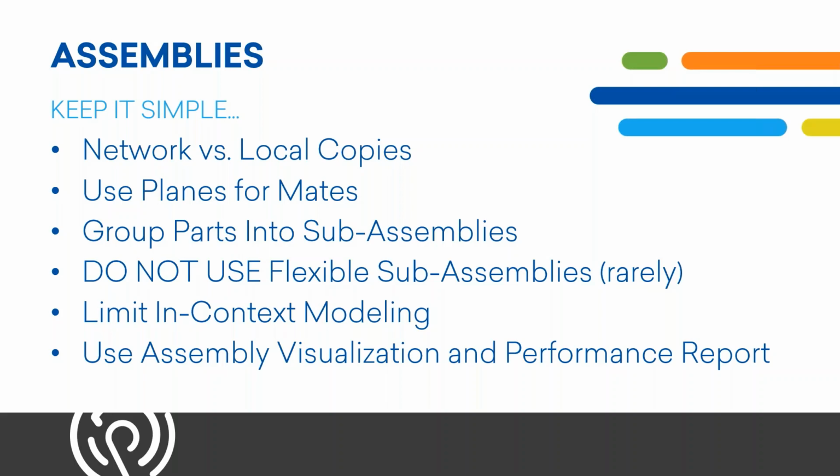Flexible subassemblies are there for a purpose, but that purpose is usually temporary. That means it's going to allow you to move things and see whether or not the working operation is correct. But once that is finished, you should return it back to its non-flexible state, the original state that a subassembly comes in. Even just having it in the flexible state is using processing power. It's sitting there ready. It basically took all the mates that were inside the subassembly and brought them into the larger assembly. Every mate is a calculation.